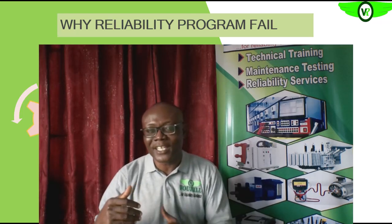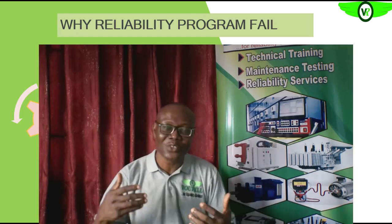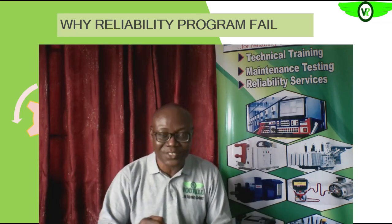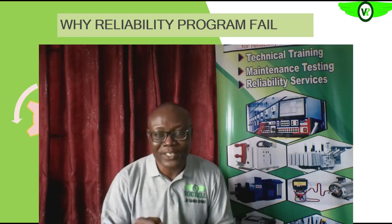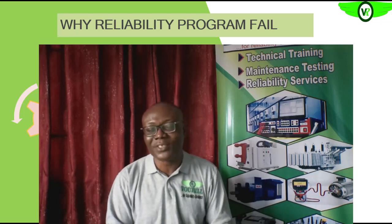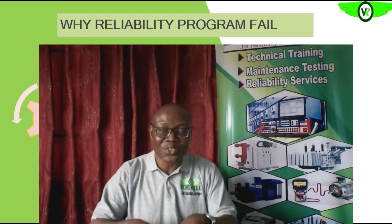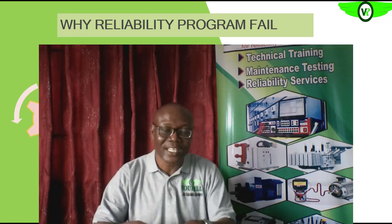So if technician A goes there and decides to use his own understanding or mind in determining the right torque level, the tendency, if he has that strength, is over-torquing that bolt, since he has nothing to measure the torque, straining that bolt, and at the end of the day, you have loose joints that will result in a leak at that joint, or that may result in misalignment.